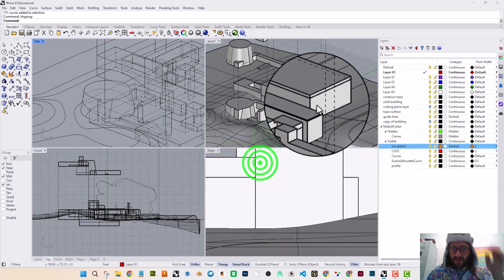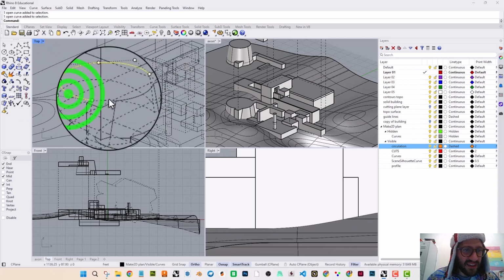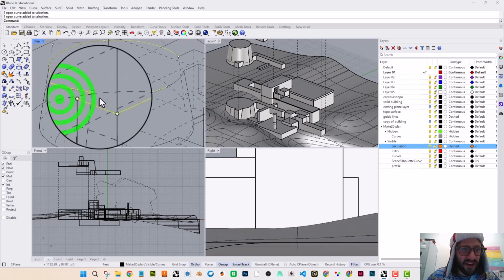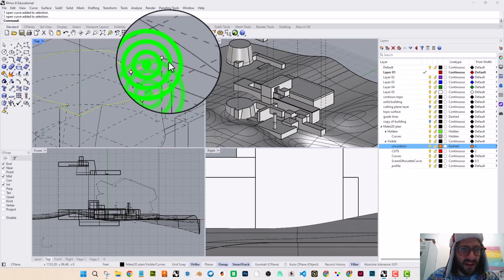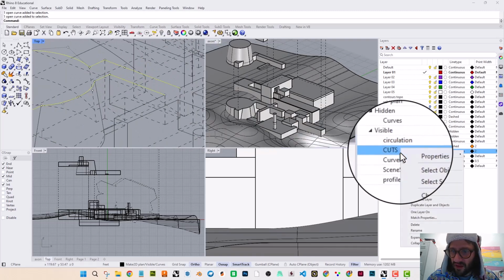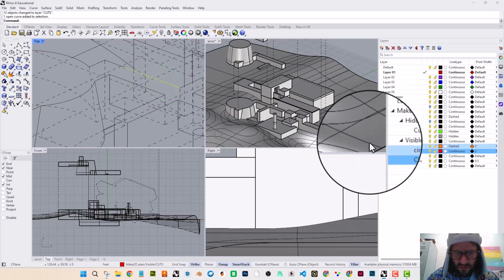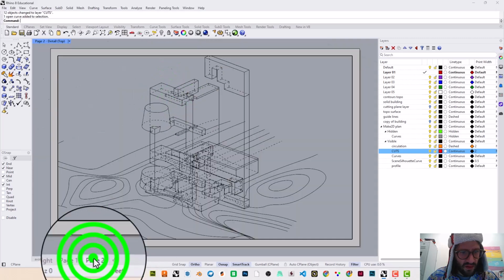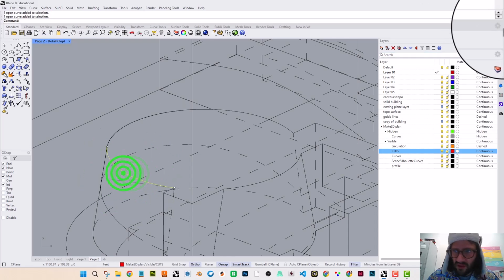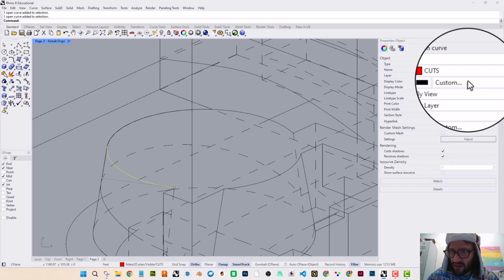I'm not able to do a full tutorial here. Okay, but I'm selecting these layers, and I'm going to say, okay, these are going to be on the cut. So then I change object layer there. And okay, let me just check. This is on the cut layer. Display color.